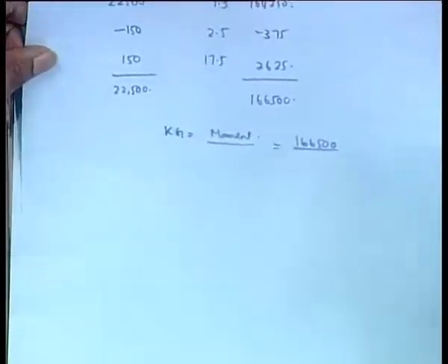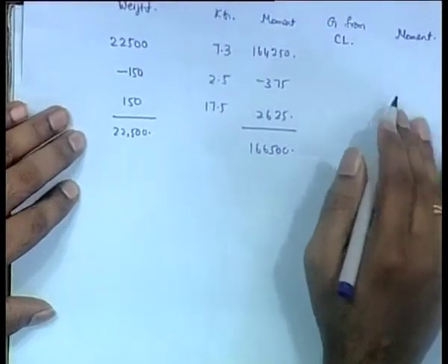Now, to do this we need one more thing. This is the first part, then you have to find how much it is moving, the horizontal moment. This is to find the shift G0 G1, that is the shift in the G0 in the horizontal direction because of the shift of the weight in this direction. So, from the center line, it is initially at the center line at 0, and then it is moved to port some distance, 3 meter, and as a result of this you know that the center of gravity of the whole ship will shift a little to the port side.